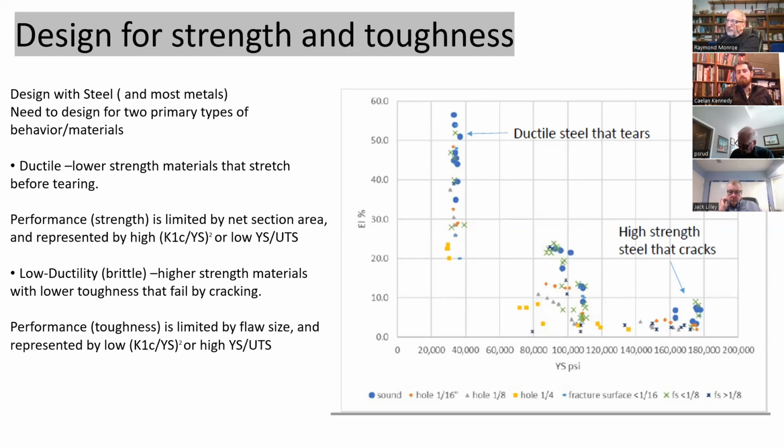So that's really a fundamental challenge. So there's about 3 things when I have test specimens that don't meet one of the properties that I recognize, which is the redundancy in it. If I meet the ultimate strength and not the yield strength, I'm not particularly worried, because the ultimate strength is the best measure I have.